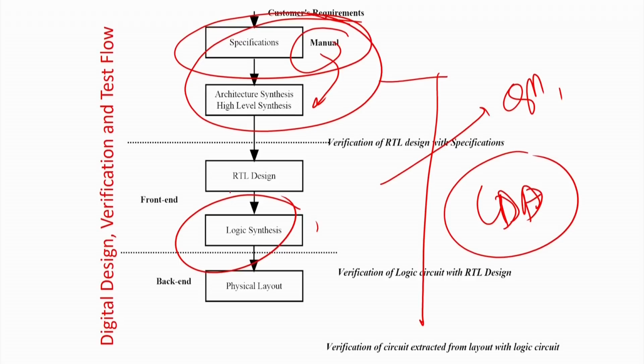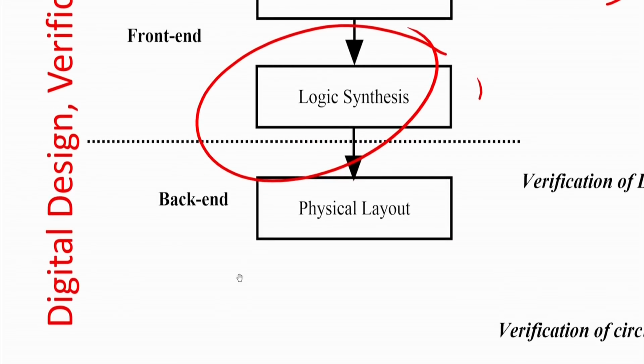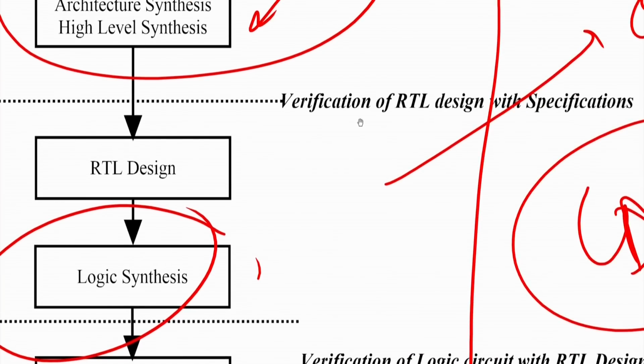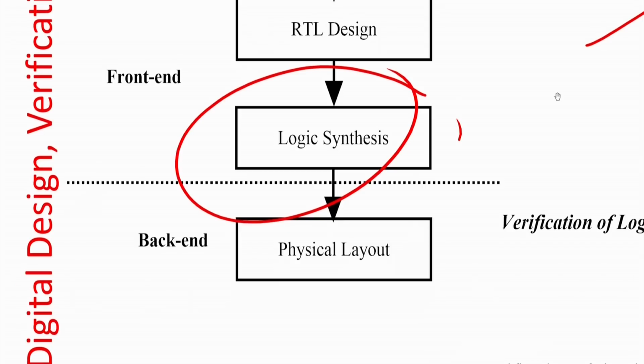So here, the optimization in terms of CAD algorithm I can call Espresso. Quine-McCluskey is a normal algorithm, and Espresso is an optimization of that, because it can solve the gate level design in an extremely fast manner. Similarly, all these optimizations will be discussed, but the only thing is that after this first dotted line, it is based on the optimization of the CAD tool, not on the input side. It is on the CAD tool which automatically synthesizes the circuit for you.